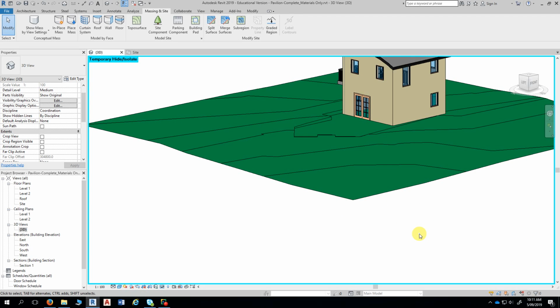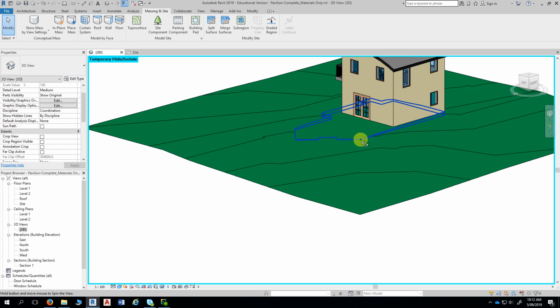And a pad is designed to go underneath the building, and essentially what it does is it cuts the terrain. So maybe on a sloping site, it would assist you in actually cutting a volume of the earth out of the terrain to accommodate the building itself. So cut and fill. And the pad tool is quite useful for other purposes, such as roads and paths, because it cuts through the terrain.